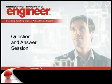Well, I'm not aware of a current limiting circuit breaker. I'm not aware of one that exists. A current limiting fuse is a different animal. A fuse will actually limit the amount of current that the downstream device sees, but I'm not aware of a current limiting circuit breaker.